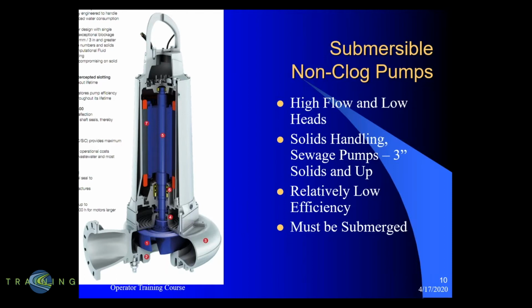Just so you guys know, one of the things that differentiates us and Flight is that with both Grundfos, who we represent, or with ABS, we pass a 3-inch solid. Flight, with their N impeller, uses a cutting ring on the inlet of their pump and shreds their solids before they pass it. That doesn't really do what a non-clog pump is supposed to do, but they've done a great job of marketing and getting approval throughout the country. So that is a difference.